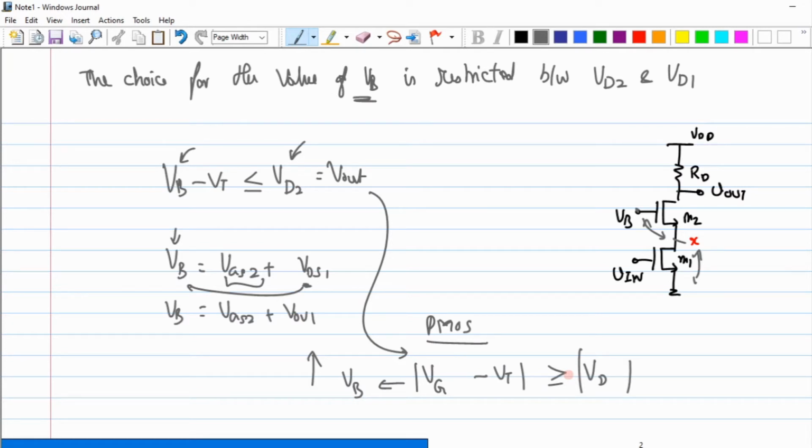So now, how would we build it? I got an idea, but I need a circuit out of it, right? So how do we do that? Did you really understand the main problem with the cascode amplifier? I have a value of VB that cannot go up just because this guy is hitting me. I cannot step down just because the VDS is defining me a minimum value here. So it's been stuck between both of these.